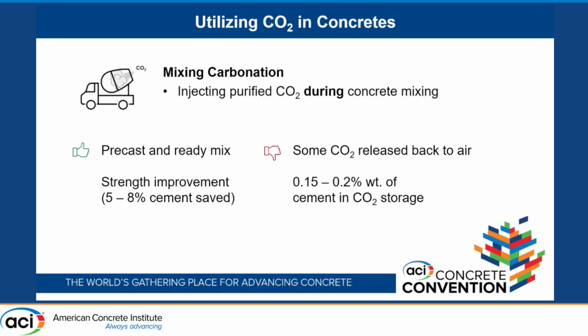The second way that the industry utilizes CO2 is injection during the mixing process. While the cement, aggregates, and water are being mixed, it is injected with purified CO2. This can be used for both precast and ready-mix concrete, and we do see a moderate strength improvement with this. We see about 5 to 8% of the cement saved during the process. However, it does release some carbon dioxide back into the air, and only about 0.2% of the weight of the concrete is utilized as CO2 storage.